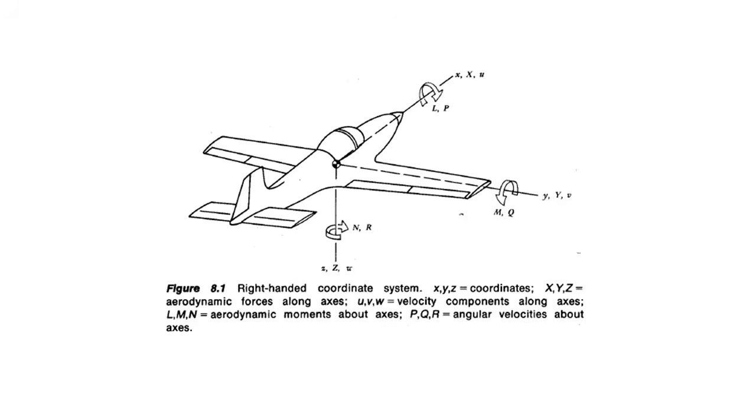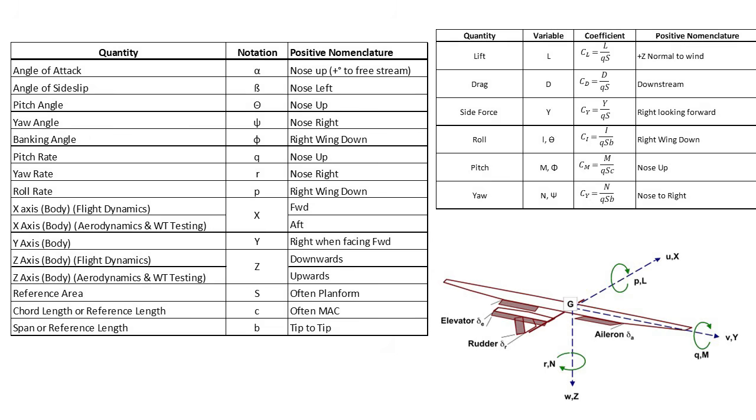Stability derivatives are essential for studying aircraft dynamics, but they aren't sufficient on their own. They must be associated with a defined reference condition that encompasses all the variables in the force and moment equations, and in most cases, the reference values are straightforward. For instance, the goal is to fly the aircraft without sideslip, right? So the reference value for beta would be 0. Similarly, during straight and level flight, body rates are nearly 0, making the reference values for P, Q, and R also practically 0. And with equilibrium body rates set to 0, it's natural to assign 0 as the reference values for the rudder and aileron as well.